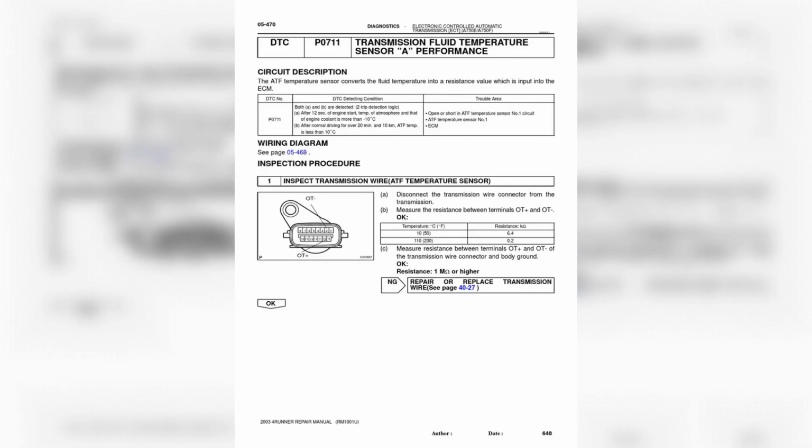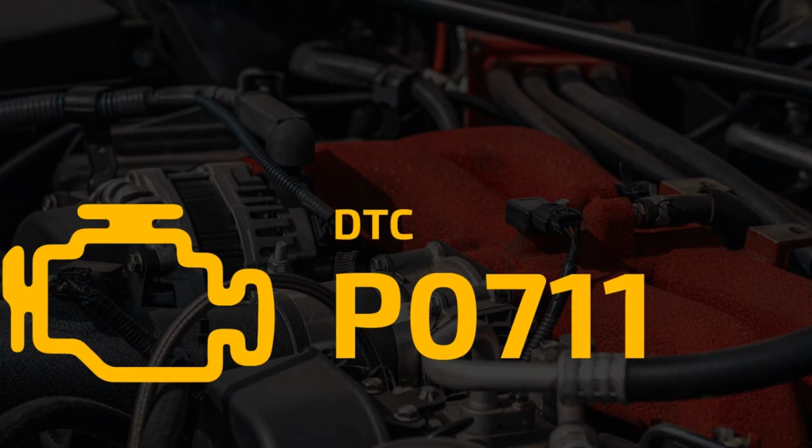Disconnect the connector and carefully inspect the terminals inside the connector. See if they look burnt or have a green tinge that indicates corrosion. If the terminals need cleaning, use an electrical contact cleaner and a plastic bristle brush. Leave to dry and apply electrical grease to the contact areas of the terminals. Using a diagnostic tool, clear the fault codes from the memory and see if error P0711 returns.